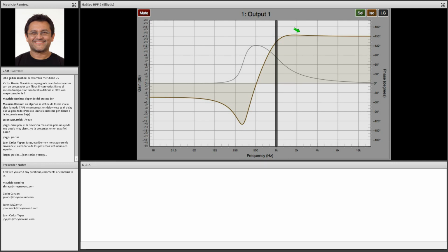And in the processor Galileo, the name for this filter is called elliptic. What is the stop band attenuation? Let's count how many divisions of 3 decibels. This is 3, 6, 9, 12, 15, 18, 19, around 19.5 decibels of roll-off. And this same filter is implemented in the analog controllers LD1, LD2, and LD3 without the flexibility to change the frequency range so much as in the controller Galileo.